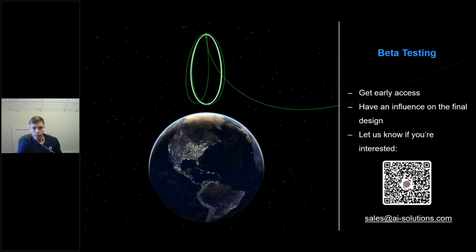Okay, and then another question. Would you recommend using the targeter to get seed values, or do the new enhancements allow for worse initial guesses? Using the targeter to find an initial solution is definitely a valid approach. It's not something you have to do. You can generate an initial guess and feed it right to the optimizer without doing any targeting. It's really up to you as a user which way you want to go about it.